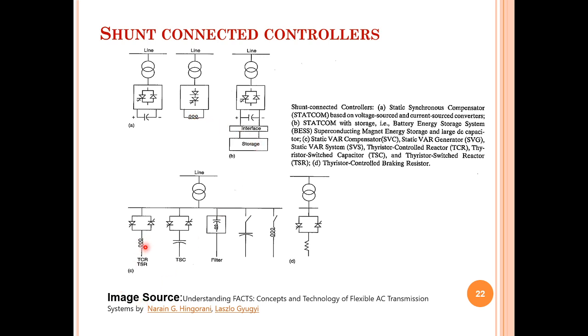If I'd like to use only a reactor, that is a thyristor switched reactor. TSR stands for thyristor switched reactor. TCR stands for thyristor controlled reactor. If I'd like to place a capacitor here, it is a thyristor switched capacitor. Just LC means it's a filter. These are the different categories. This diagram is for STATCOM. STATCOM's full form is static synchronous compensator. Static synchronous compensator is an example of a shunt connected controller.